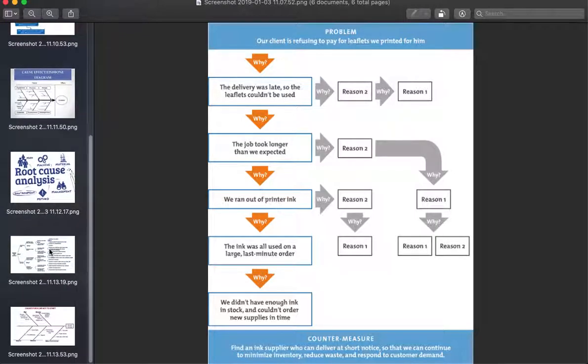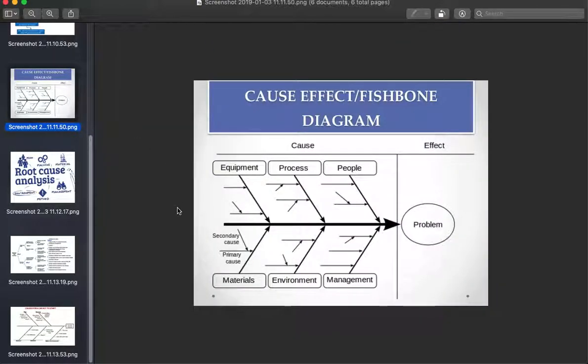Let's look at a few other things here. If you've never seen a fishbone diagram, this is a fishbone diagram. It's a guidance tool to help you find the root cause of the problem. As you unpack these things, could the equipment have been an issue? If it was, then what was it? And you start to prioritize these causes and unpack them. Sometimes it's more than one cause, or sometimes it's a symptom disguised as a cause. So thinking holistically about the whole environment, you may think, well, we've got a machine equipment problem because we're getting arcing in our print.